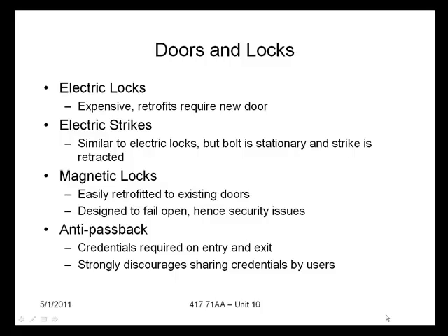Now, electric locks are a very secure mechanism to control a door. They actuate the door bolt electrically rather than mechanically. Electric bolts have built-in position switches and request-to-exit hardware for safety purposes. They can be expensive, though. A special door hinge that accommodates the wiring harness and internal hardware is required. For retrofitting, electric locks usually require purchase of a new door.